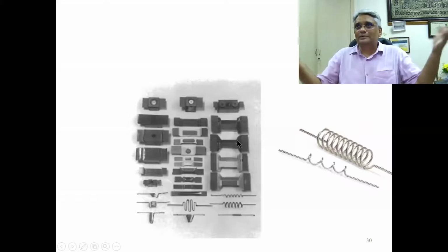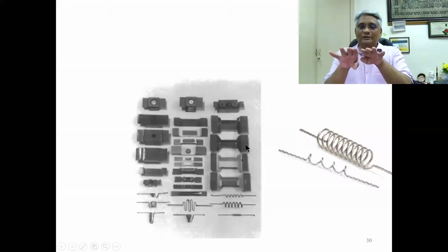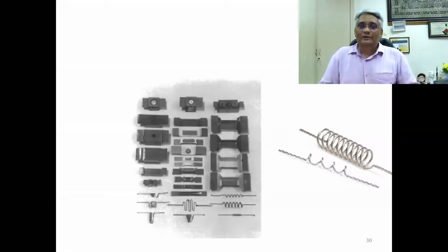It just spreads, gets liquid, and that means the area of the evaporating element has increased. Okay, and there is also a possibility of a reaction happening between the crucible material or the boat material and the molten element or alloy.